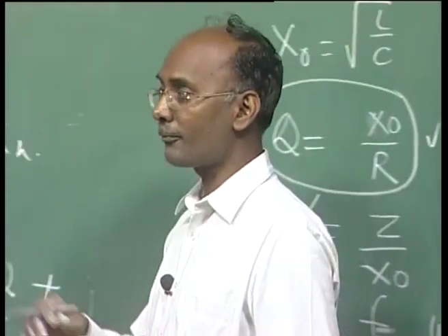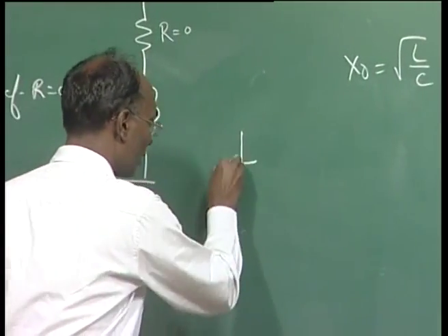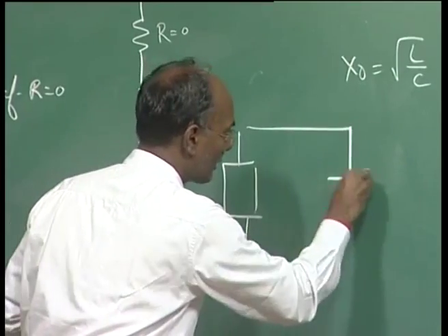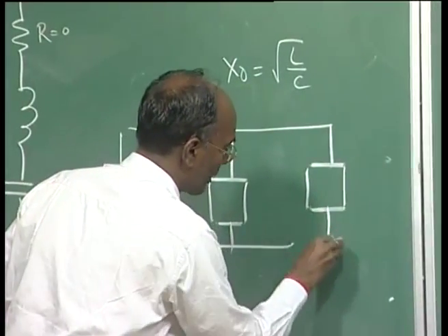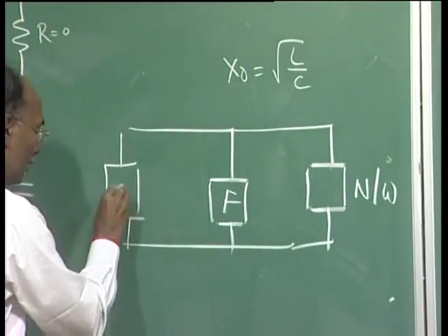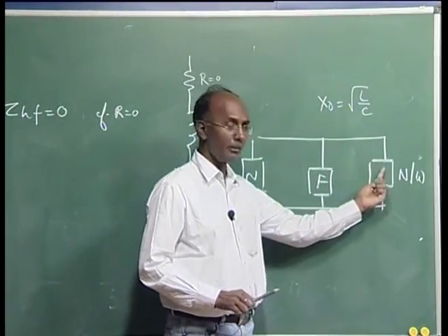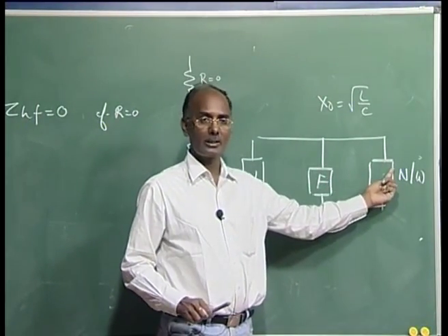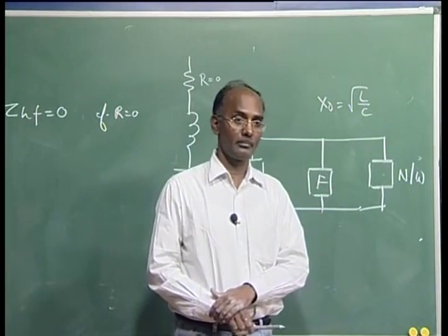And if resonance forms in the network, here this is your source converter, this is your filter, this is your network, this is your source of harmonics. So, there is a possibility that if the impedances resonate with each other, then a huge voltage arises across this, and that is also not desirable.